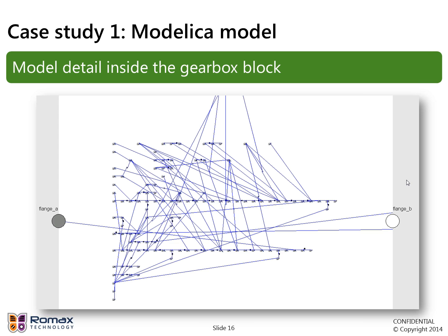When you open up that Modelica block representing the gearbox and have a look inside, you can see why it's necessary to have something like DynamicFUSION. As soon as we move to these higher frequencies and we need this higher level description, you can see this model is now pretty complex. Each one of these dots here is another block representing each of the masses within the model, and obviously they're all connected together by various stiffnesses, also by gear meshes. Some of these links will be gear meshes, some will be synchronizers, and so on. So you can see just how complex these models can get.